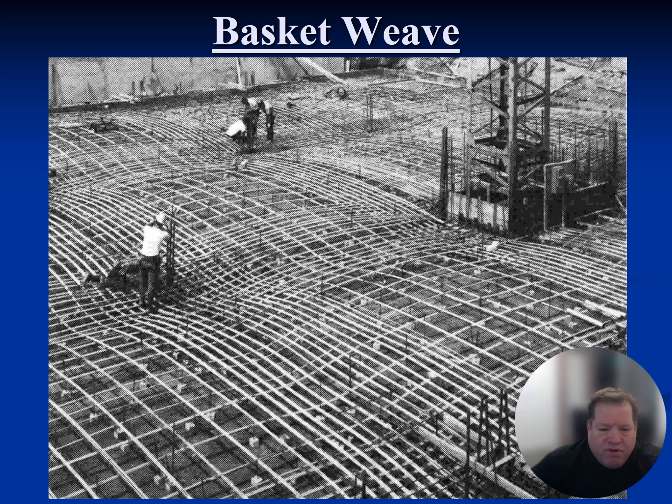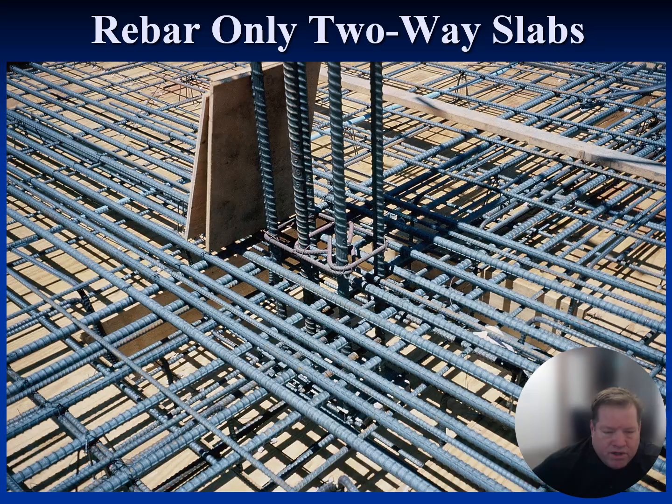And this is a photograph from one of those back in the day, obviously the sepia tone to indicate the passage of time, but hopefully you can see the column strip here, a whole bunch of PT, the column strip here, a whole bunch of PT, less in the middle strip portions. And as it comes down to the support right here, all these things want to be in the same zone. So you have a lot of post-tensioning, then obviously some rebar, which is going to be tough to see, intermingling with each other. And trying to get this stuff threaded to be everything at the right location to the best of your abilities, again, was extremely challenging. And challenging is not something you really want in a general construction practice for your material.